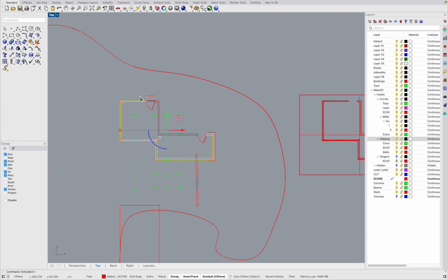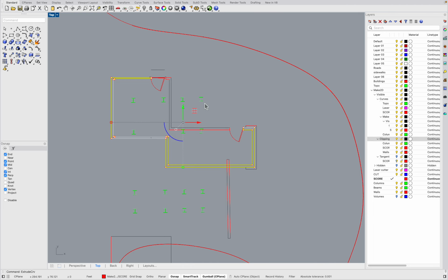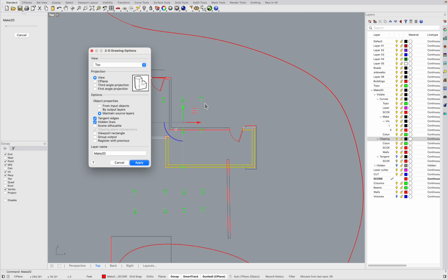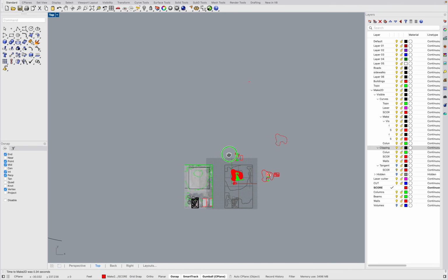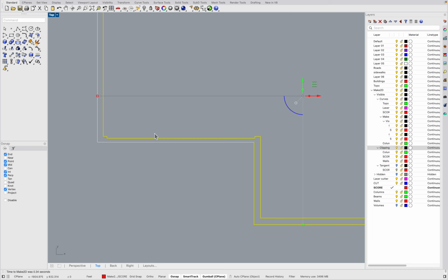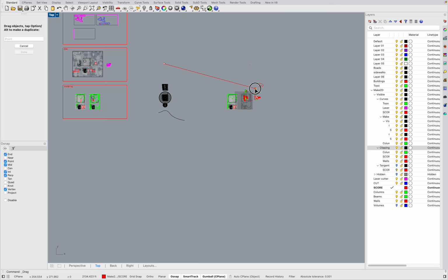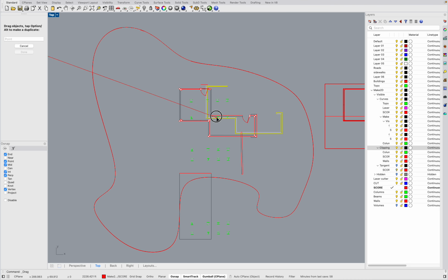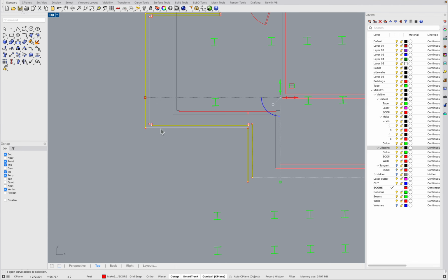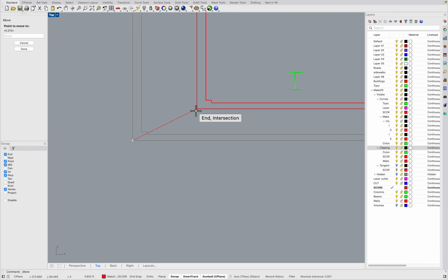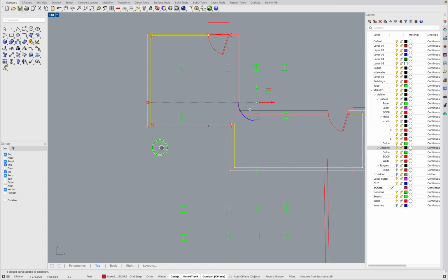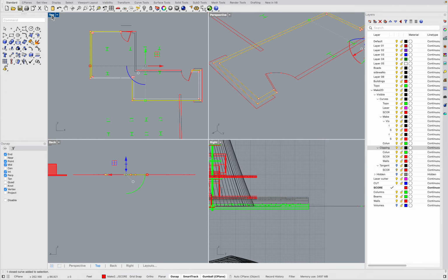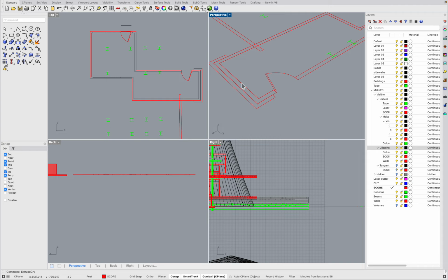So in those cases where it's really giving you a hard time, what I would do is make it 2D, because it could be something that's just not flat. Check all your bases. Take that guy, bring it back. We'll move it again. Probably switch the layer up on that one, because now I don't know which one. Let's try extrude again. Nope, still got the message.